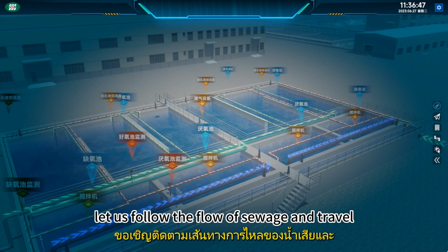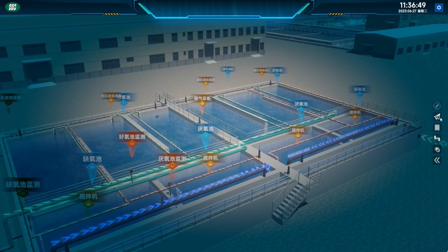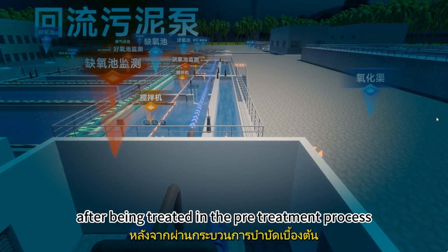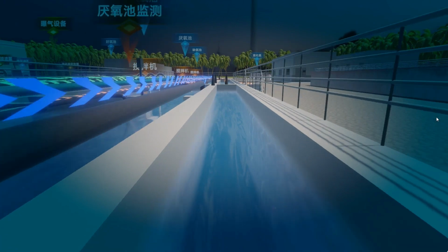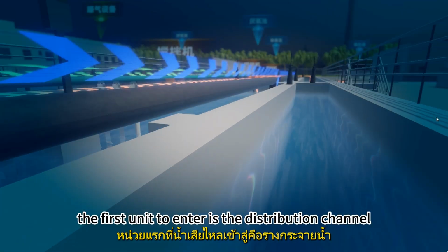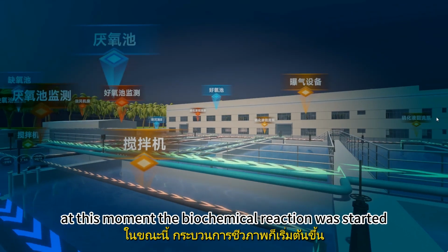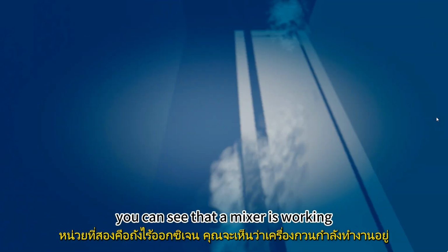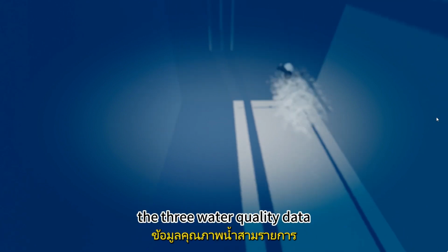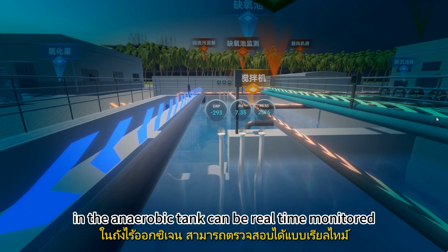Let us follow the flow of sewage and travel through the entire AAO process. After being treated in the pre-treatment process, the sewage water is sent to the biochemical section. The first unit to enter is the distribution channel. At this moment, the biochemical reaction is started. The second unit is the anaerobic tank. You can see that a mixer is working. The three water quality data in the anaerobic tank can be monitored in real time.